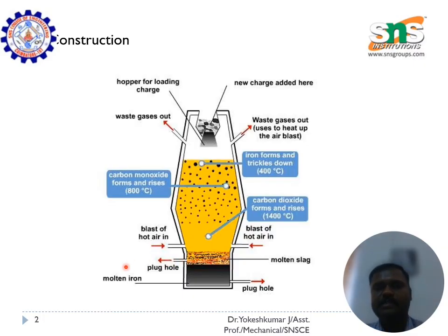So what do we mean by molten slag? When the metal is melted to its molten state, oxide layers may form on the top layer of the molten metal. The skin has to be removed properly, or otherwise it leads to pouring related defects. This skin formation is due to the top layer of the liquid metal being in contact with atmospheric air, which reacts with oxygen and forms iron oxide. So this iron oxide is formed as a slag. We have to remove it.